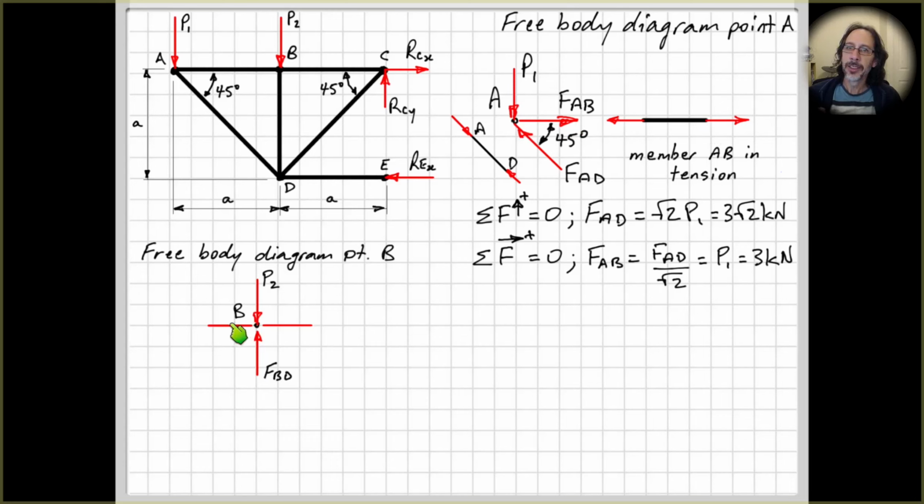Okay, so down here we need to put the arrow acting to the left. And now that we know that, and we note that FBA was FAB, you can just call them both FAB if you want, doesn't really matter. The force on the other side in member BC must be equal and opposite to that, so therefore must be acting to the right.